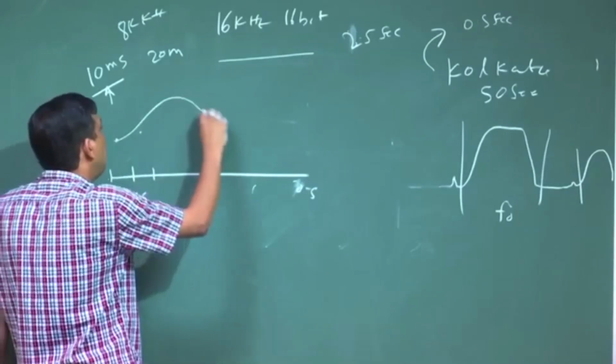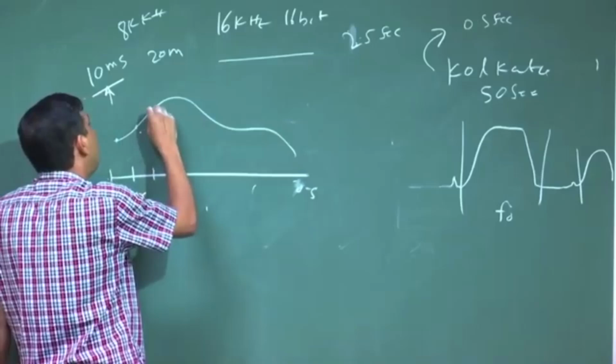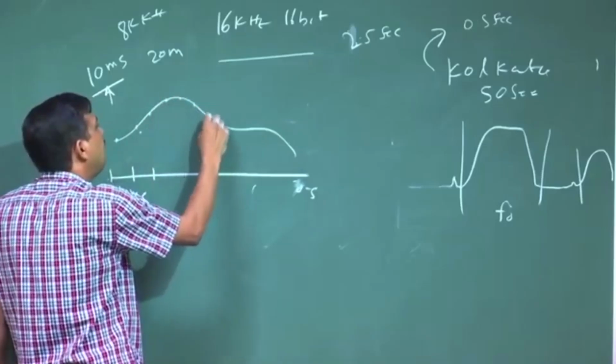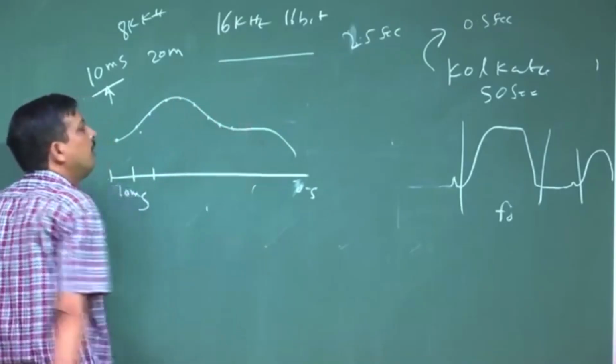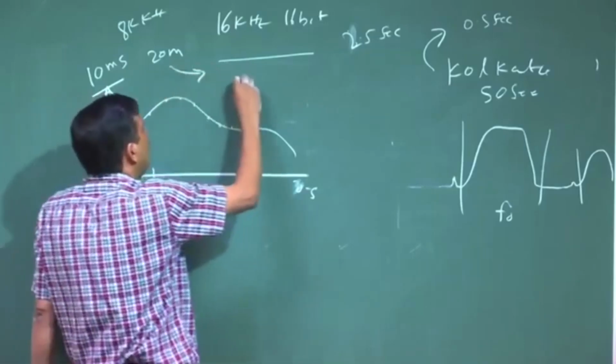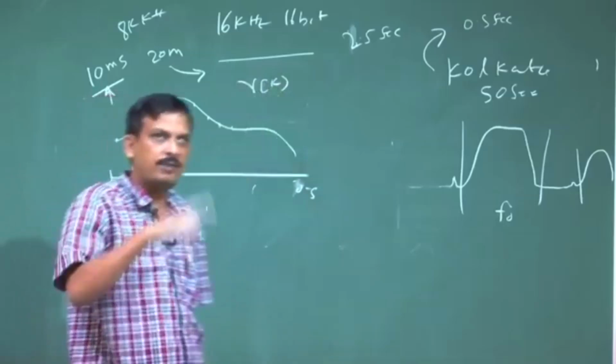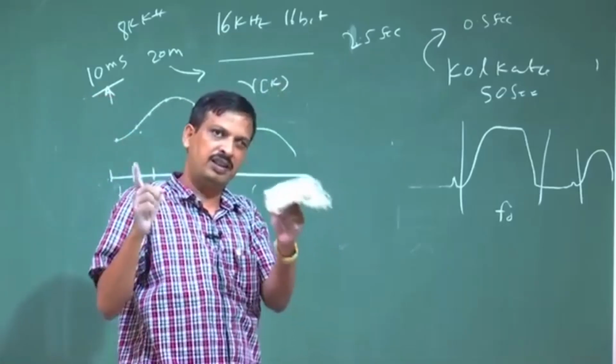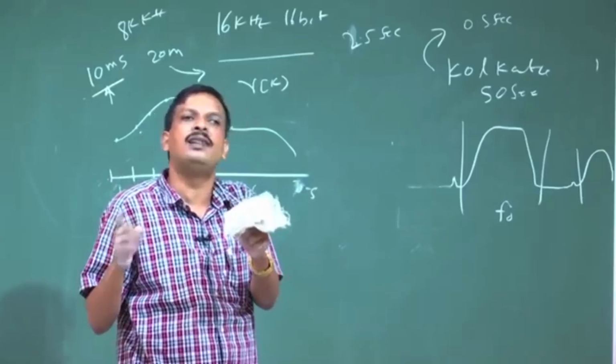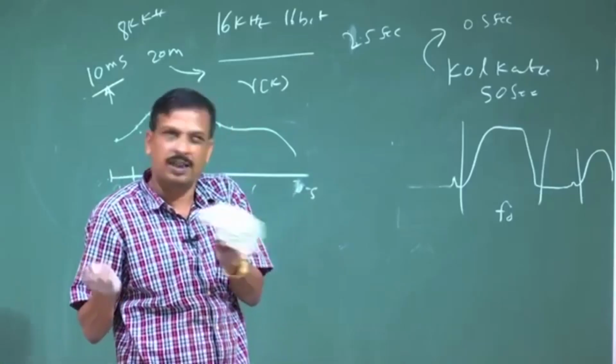So, I can get the F0 contour in which each point is 10 millisecond apart. So, for a 20 millisecond signal, I will calculate the Rk value and find the maxima, the first maxima, then calculate the lag, 1 by lag is the frequency, and I can get the F0 value.